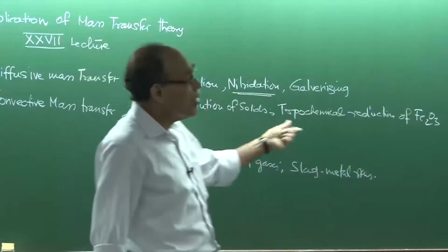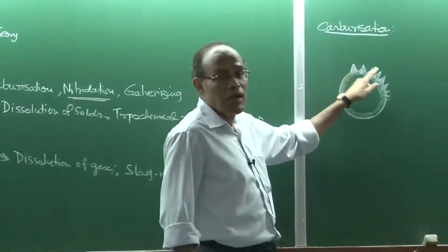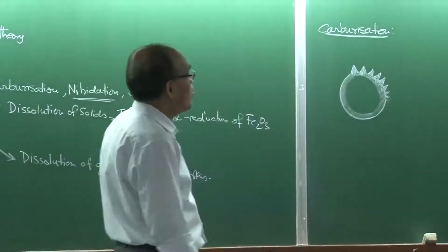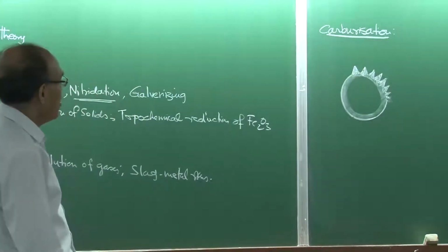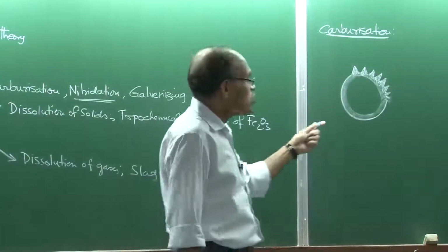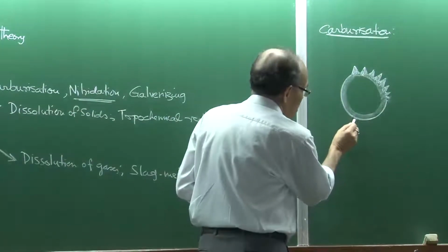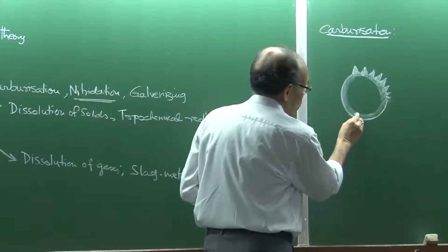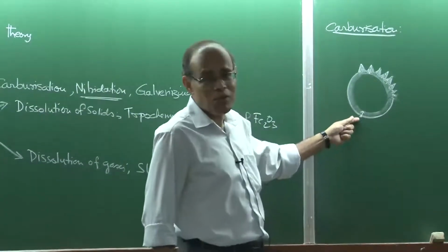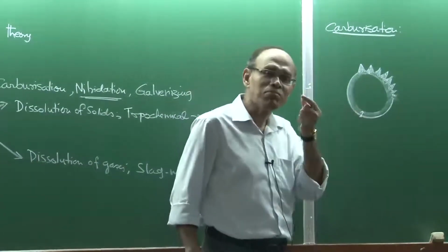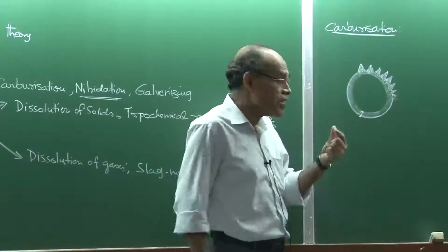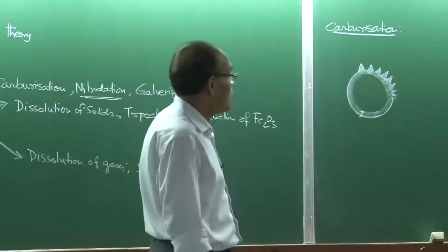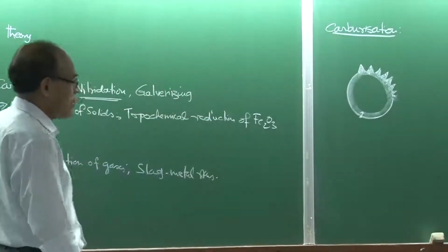Similarly, you can have a nitride phase also forming because of the nitrogen diffusion, which can enhance the hardness of the surface. And because this is happening from here, the transport of carbon and nitrogen is happening purely by a phenomenon of diffusion. So that's why the process is slow. So the carburization, if you want to have 1 millimeter, 2 millimeter thickness, you have to carburize the samples or nitride the samples for a longer amount of time, in excess of several hours, for example, and then only.